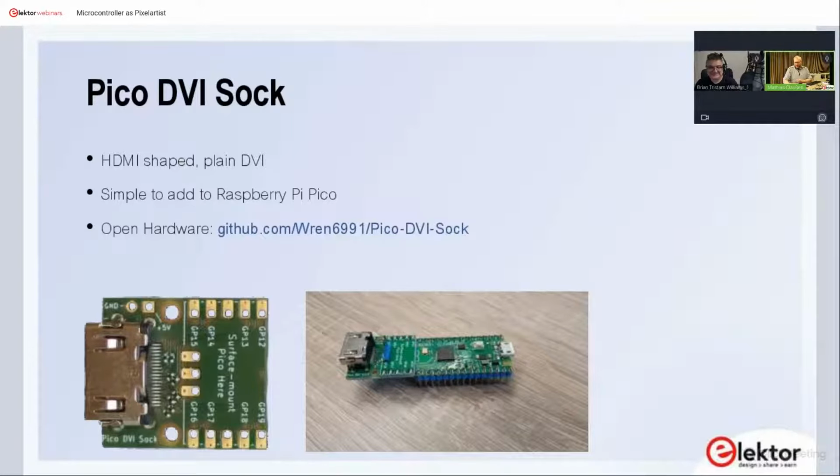Nevertheless, we got a question about racing the beam. We'll get back to that a little later, when talking about sprites and sprite stuff with the image creation. So racing the beam means you have to output a data stream to get the monitor displaying something. You can't stop. You have to push a constant amount of signals in a timely manner out of the system so that the display will be able to show something. A monitor was expecting the control signals for the beam at a certain timing,